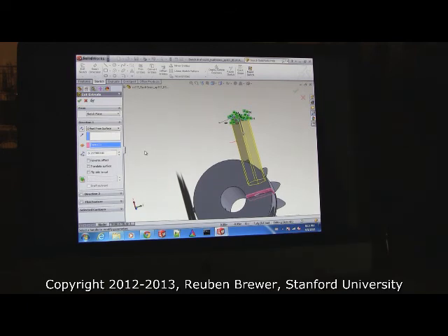Which surface do we do the cut from? See this one here, the pink one? Yeah. It's basically the next surface that you would intersect. Can you just quickly repeat what you did after setting them all equal? Yeah, so then take smart dimension here, and then click between two opposite sides. Two opposite sides? Yeah, so flat. Imagine you took it and pinched it between two fingers, and set that to 5.5 millimeters.